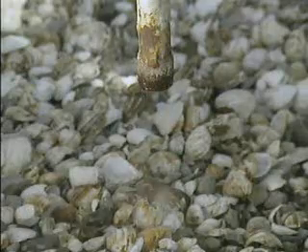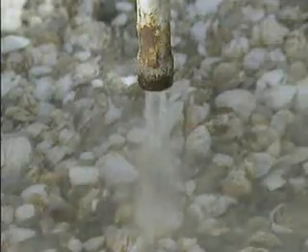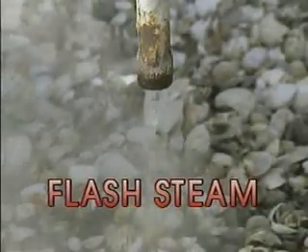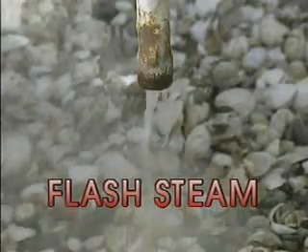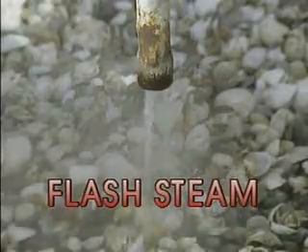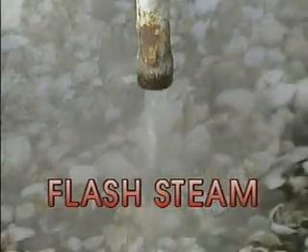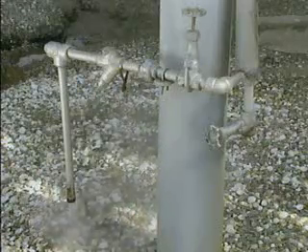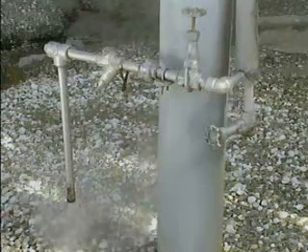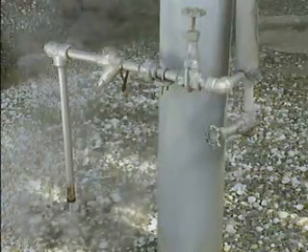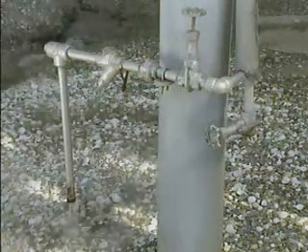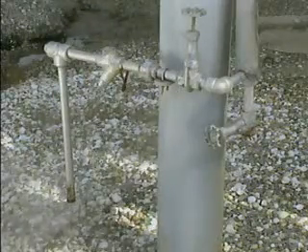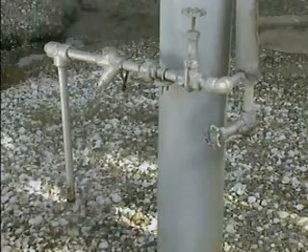Another type of steam that's associated with industrial steam systems is flash steam. Flash steam is normally produced when sufficiently hot condensate that's under relatively high pressure is discharged to the atmosphere or into a lower pressure line. The decrease in pressure causes some of the discharged hot condensate to flash into steam. The production of flash steam when a steam trap discharges is generally a normal part of trap operation.